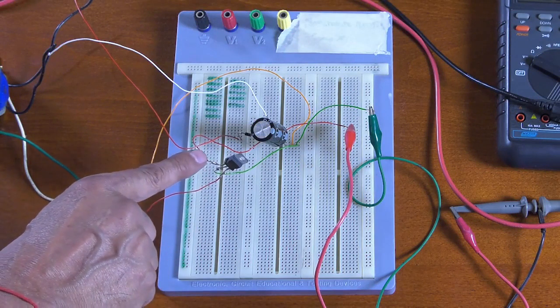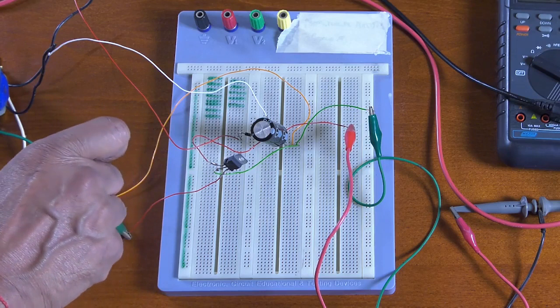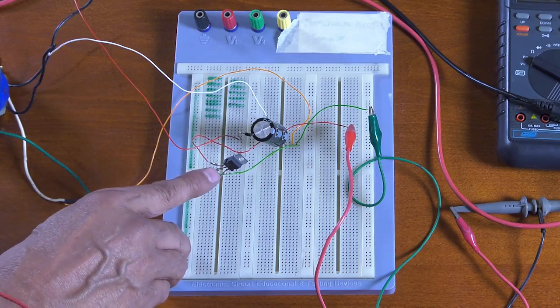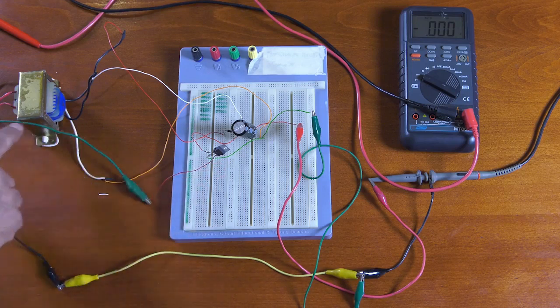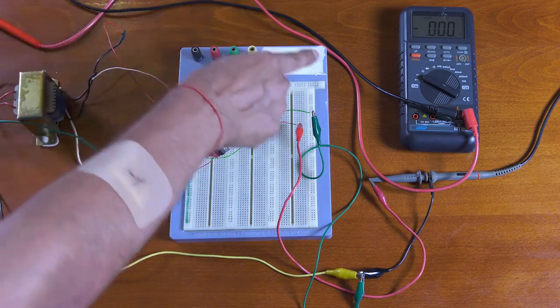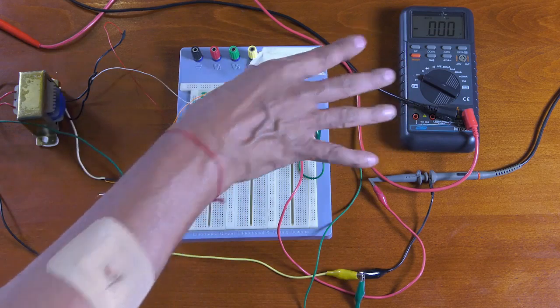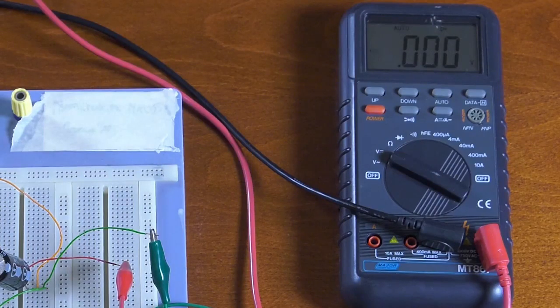This pin is in, which means it comes in from where your 2 diode cathodes meet, or where the positive of your capacitor is connected. The center pin is your common pin. The last pin, the 3rd pin here, is your output. If I connect my output to my multimeter like so, and if I connect my common, which is common to everything here, like so, and if I power up on my multimeter, I should see a nice 12 volts or very close to 12 volts DC power supply. And that is the completion of the power supply circuit.